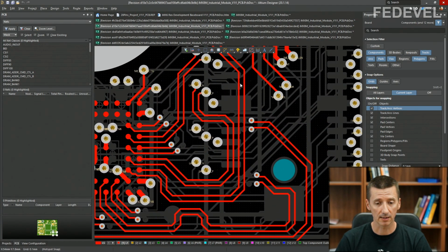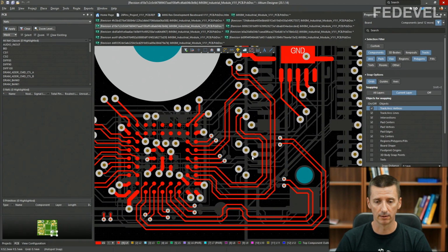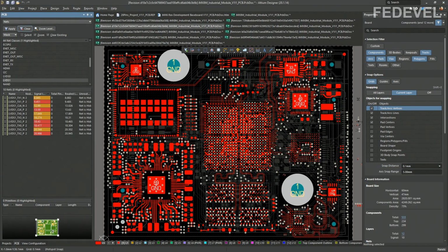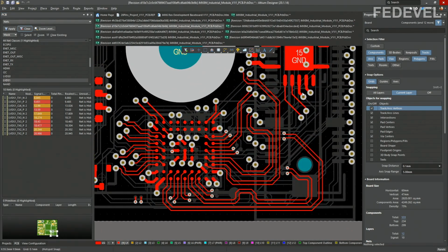I know this is still a draft, but even in the draft you still need to think if there will be space to improve this layout, if there will be space to move these differential pairs far away from each other. A little bit later, we will have a look at how the layout of these differential pairs was improved.